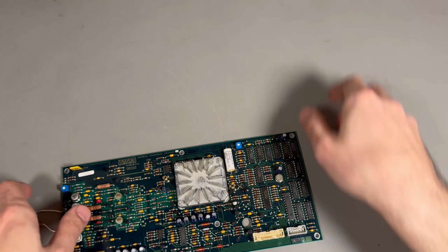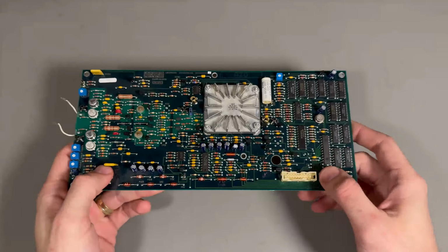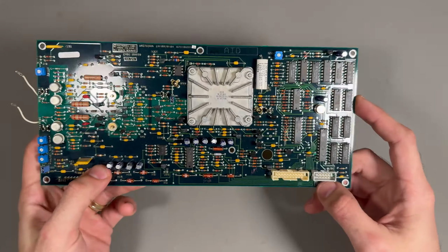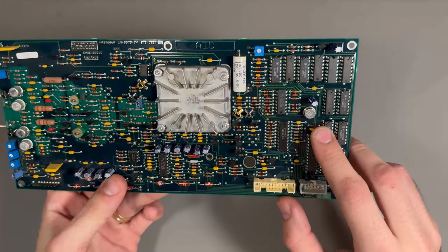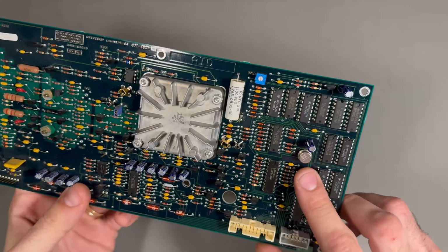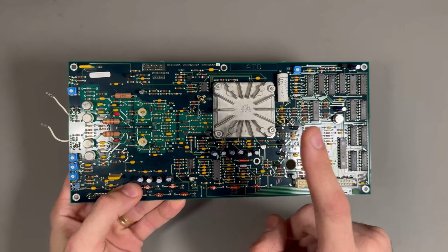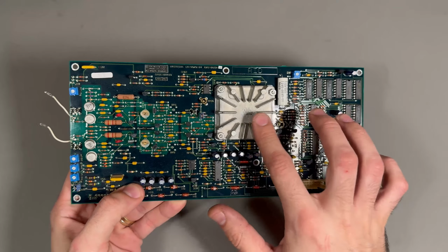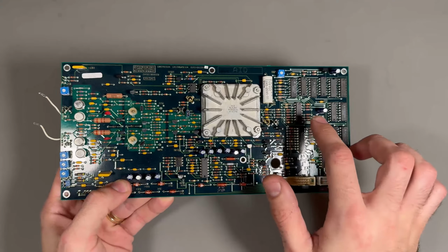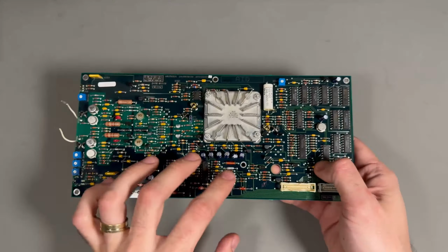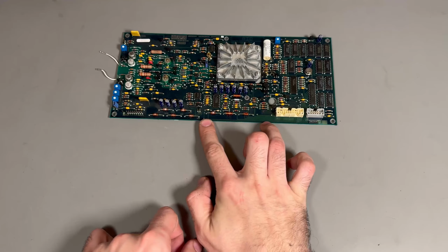So this is just a very precise time base and very fast as well, because you need to sweep at very high speeds to get any reasonable information out of a very fast pulse. And interestingly enough, here there's an AD581JH, which is a 10-volt precision reference. It probably has something to do with the precision of the time base, because this is an integrator. Inside there's an integrator, and it probably relies on a precise voltage in order to get an accurate and linear sweep ramp. So this is the horizontal, the right gun.